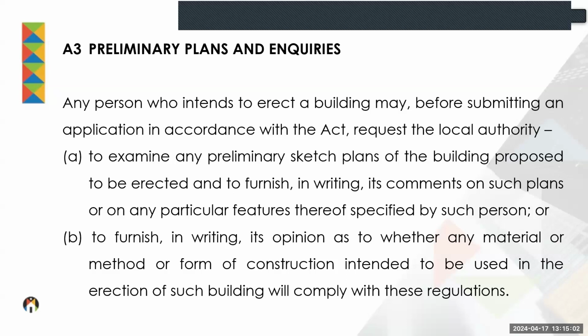And you will see that in 10.400 Part A, the regulation requires you to get that answer in writing, and that you then attach that answer that you've got after you've consulted with preliminary plans to the local authority, and they're giving you a way that they're going to look at that. That needs to be attached to the building plans that you submit, so that whoever then checks the building plans for compliance doesn't come up with another requirement, and that the original arrangement will stay in place.